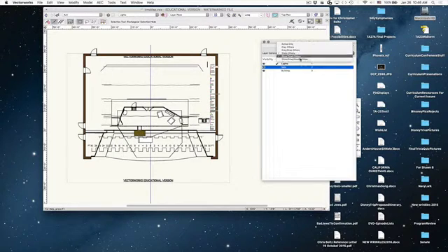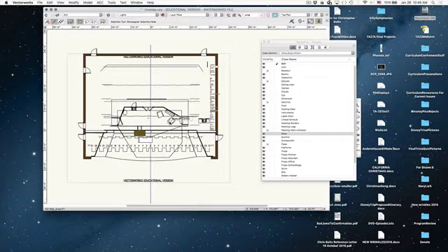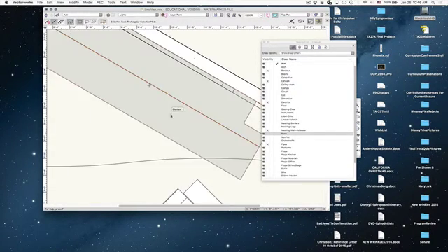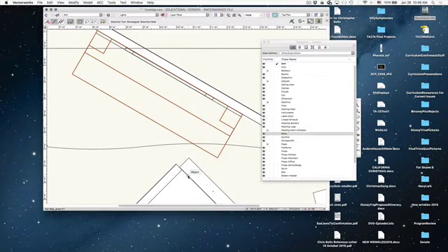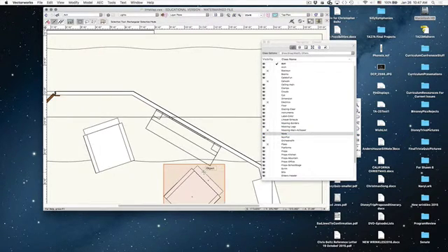And that's because, let's just show snap modify. Okay, come back here. I can only click on objects and select them, get that orange box around them, that are on my Act 1 setup. If they're not there, I can't select them, okay? If I say show snap modify, I can now select any object and edit it, okay?